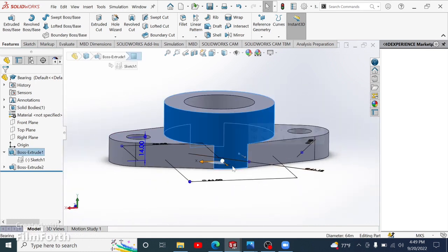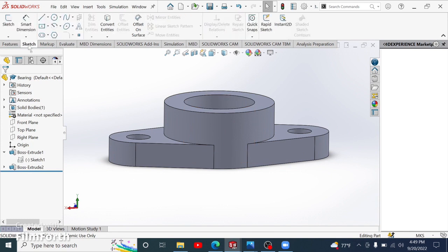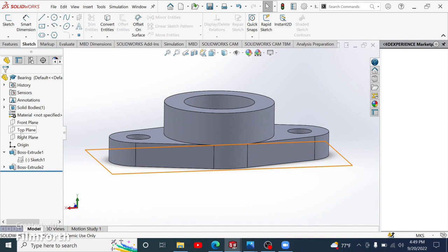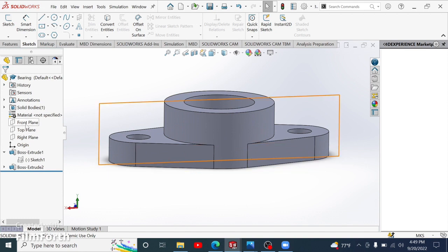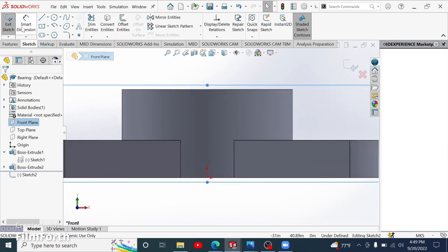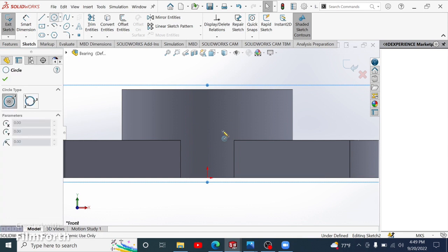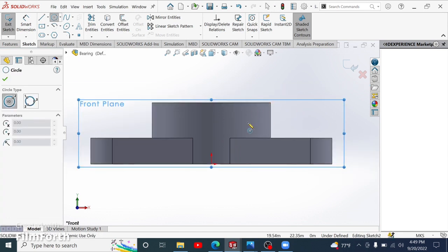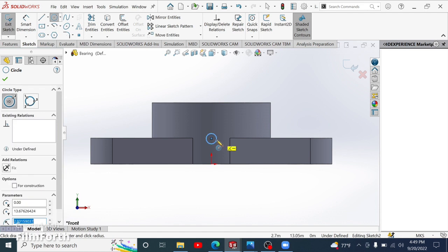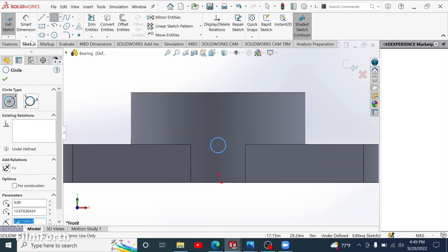And I'm going to add this guy right here on this shape. So what I'm going to do is go to sketch, new sketch, actually exit. Go to these planes. I'm going to select the front plane, sketch, and that would automatically select the new sketch right there. So you can't really tell that it's behind the circle. If I was going to trace behind it, it's not going to affect the surface. It's going to affect the plane for the inside and the middle. So I'm going to select that one, make a small circle right there, and then the smart dimension.